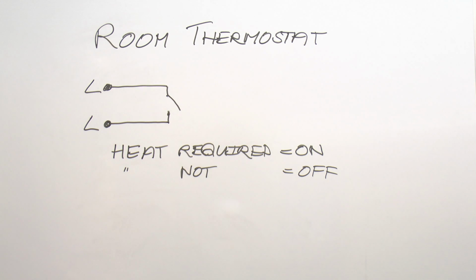However, when actually installing cabling for these, of course, you're going to be putting an earth connection to the position for the thermostat. Obviously a lot of thermostats don't need that, but of course some of them do. And normally a fair number of thermostats also need a neutral connection at the position of the thermostat.